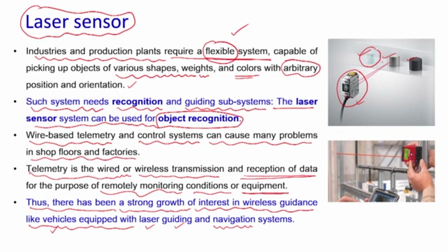The laser applies energy over the part, it gets reflected, and based upon the reflections some signals are generated. These signals are given to a microprocessor based system, which takes the necessary action. Either it records the data, or it actuates certain elements to push the part off the conveyor, or it may ask the robot to pick it up from the conveyor.